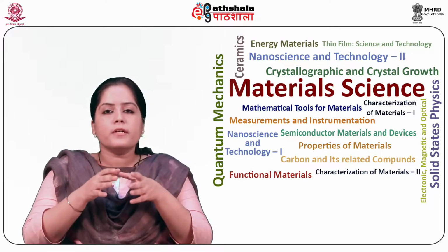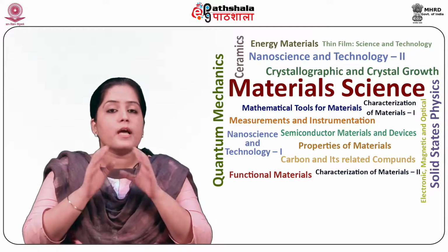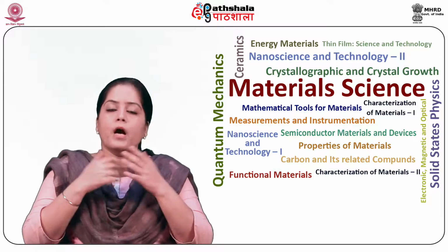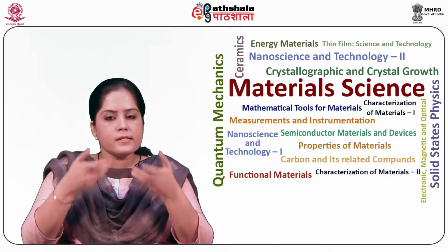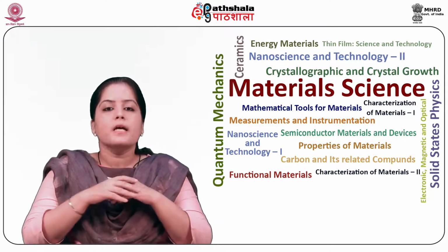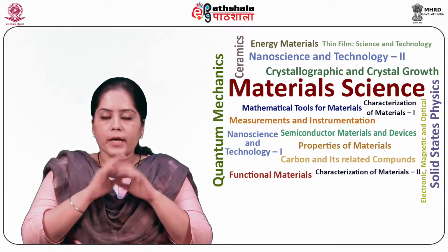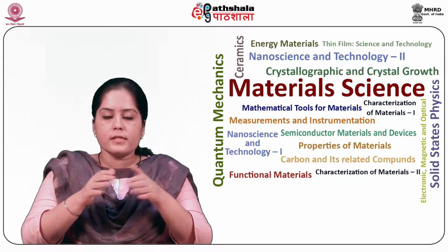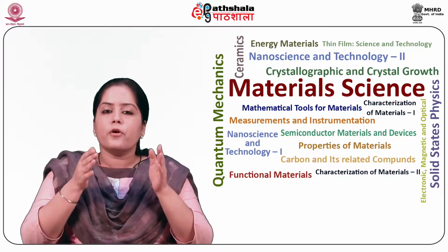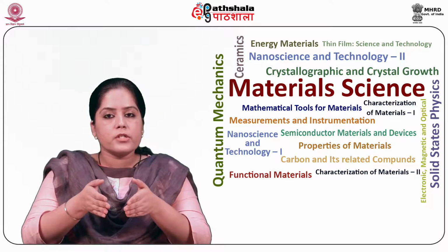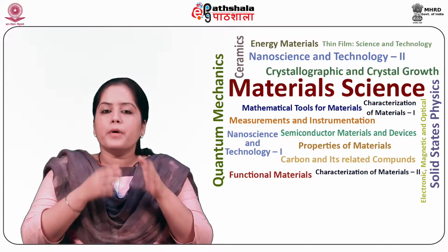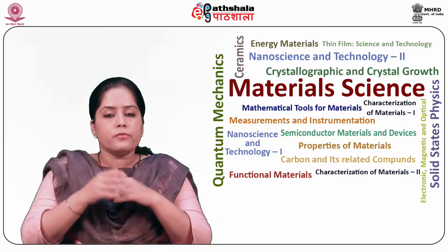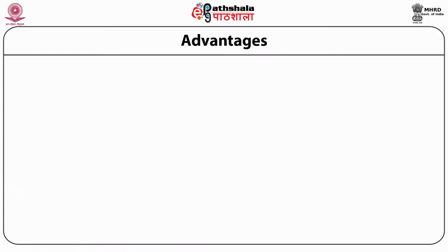One of the more important applications of the sol-gel process is to carry out zeolite synthesis. Other elements, metals, metal oxides can be easily incorporated into the final product, and the silicate sol formed by this method is very stable. Other products manufactured with this process include various ceramic membranes for microfiltration, ultrafiltration, nanofiltration, vaporization and reverse osmosis. Now let us discuss the advantages and disadvantages of this process.